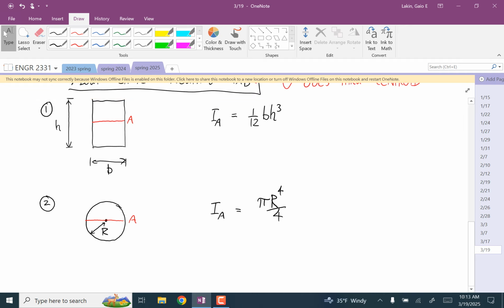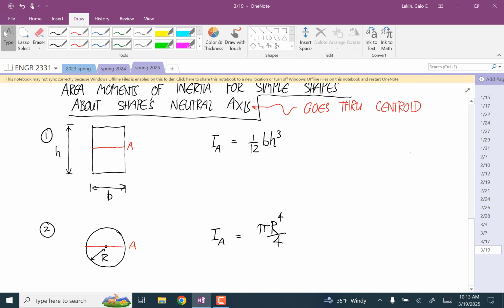Are these neutral axes parallel with the x-axis? Yes. Okay, so this would be bending or area moment of inertia about x? About z, because this is a cross section. Oh, okay, I see. So, like looking down the x-axis. Yeah, exactly. This is like you're looking at the beam, daring it to stab you in the eye. Okay, I got it. So x is coming this way, y is this way, and z is this way.